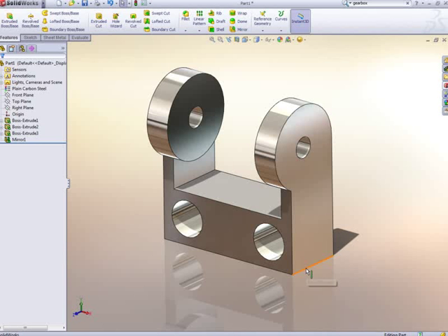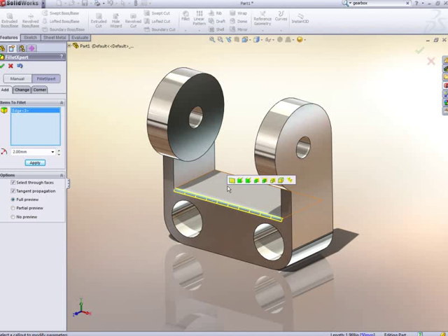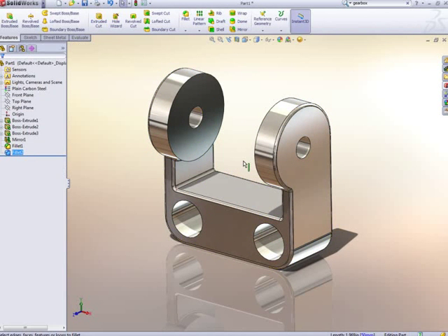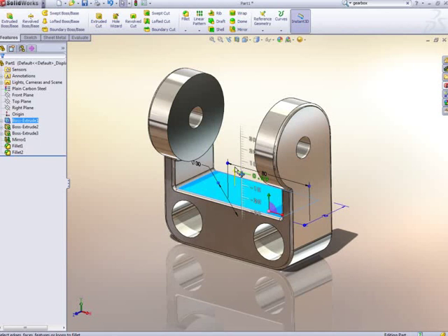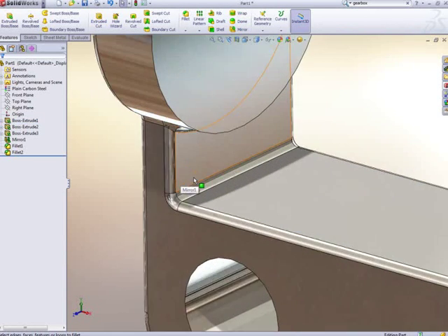Finally, remove all burrs and sharp edges. We'll add big fillets to these bottom edges and small ones everywhere else. Again, the user interface comes to our rescue, adding all similar edges to the selection, saving a lot of clicking. And there's our design. Just make a few more modifications, just because it looks so good.